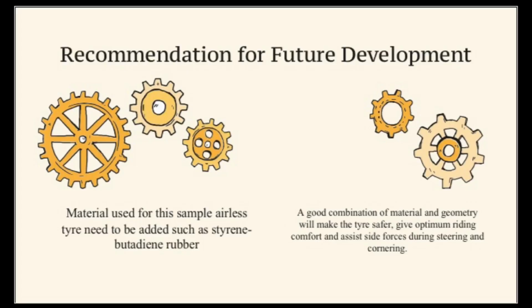Recommendation for future development. The material used for the sample airless tyre needs to be added, such as styrene butadiene rubber, and next, a good combination of material and geometry will make the tyre safer, give optimum riding comfort, and assist side forces during steering and cornering.